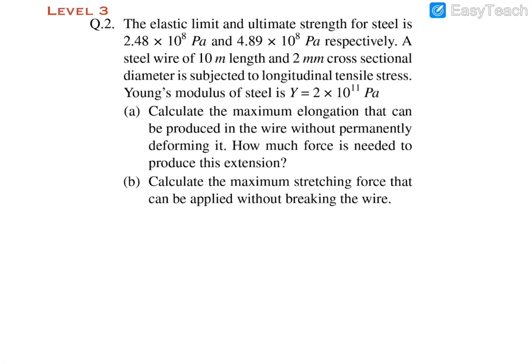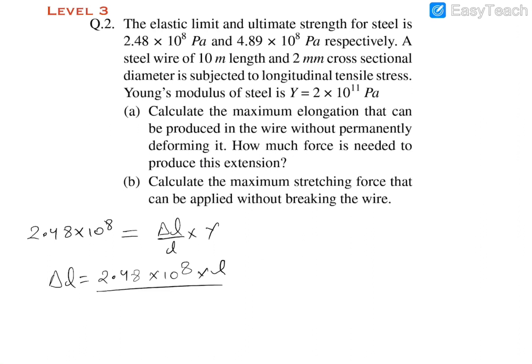So first of all, we know that elastic limit is 2.48 into 10 raised to power 8. In some cases, students are not able to understand whether this elastic limit is strain or stress. You can just see the unit. So unit is Pascal, and therefore this is stress. So this is stress, and it would be equal to delta L by L into Y. So delta L will be equal to 2.48 into 10 raised to power 8 into L divided by Y.